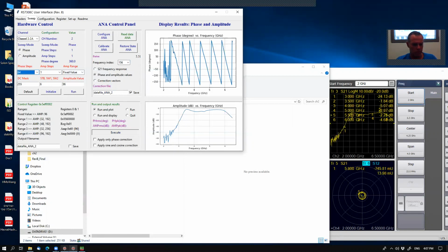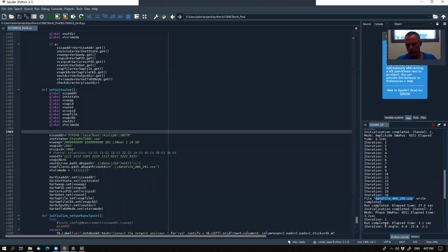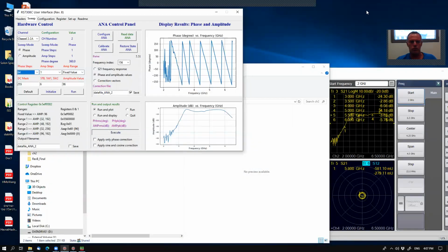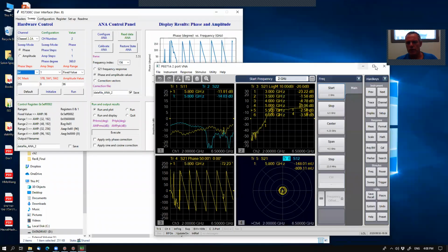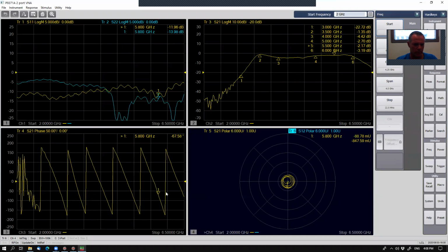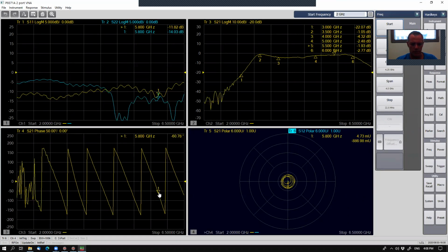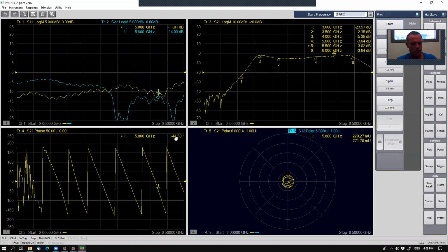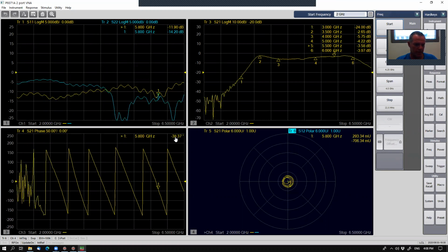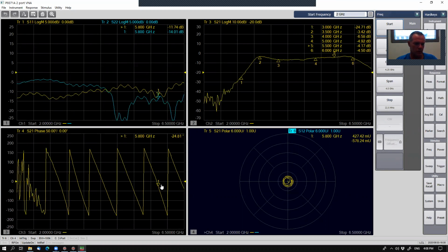And then you open the console to monitor if you have the sweep. So we have the sweep started. And it's going to end when it reaches the 64 steps that have been implemented. So one thing that you can see while the system is running is to observe the markers. So you see the markers here, either in a polar format or in a rectangular format. So the phase is being swept.